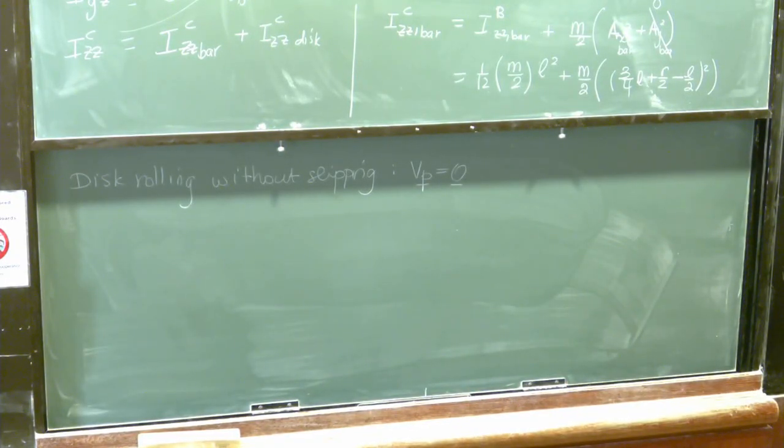Are we not able to just use the definition of friction? What is the definition of friction? Oh, because it's static. Right, exactly. You cannot say that friction is mu k times v real over v real because it's not kinetic. It's static, so it's still an unknown. So you cannot do that. Friction is an unknown, but what's known is the motion. You have this roll without slip condition. Vp is equal to 0. How do I use that to continue? Exactly. Vc minus Vp is omega cross Rc minus Rp.